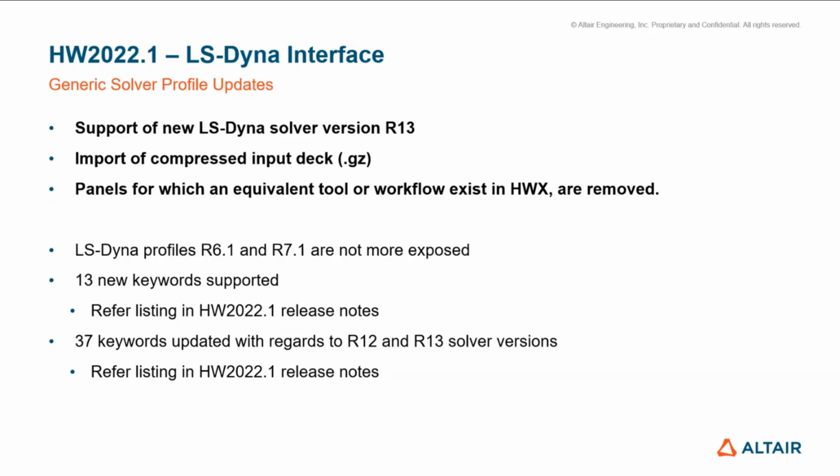We have also introduced the capability to import compressed input decks in GZ format. Basically, you can now directly read and import this type of file in HyperWorks, and it will be read totally like a standard input deck. Just understand that this is just for the import, not for the export. We don't export in compressed format.